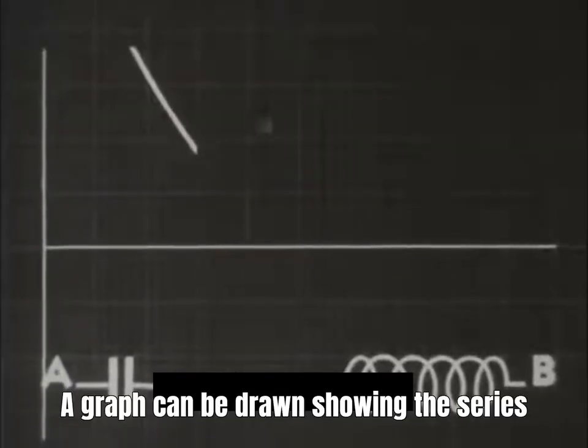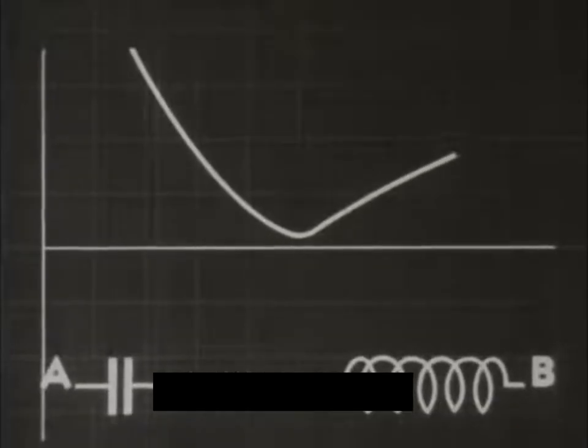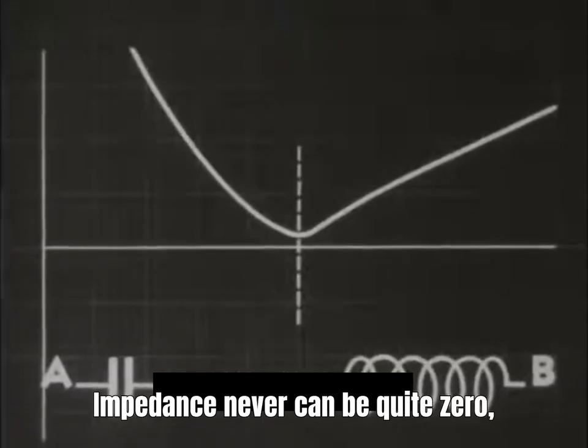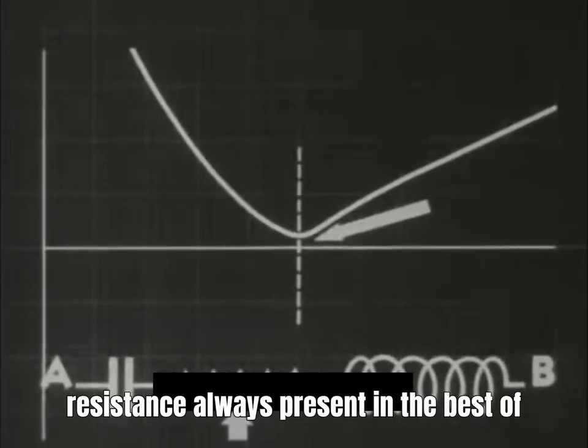A graph can be drawn showing the series resonance in terms of impedance alone. Note that the value of impedance from A to B is lowest at resonance. Impedance never can be quite zero, however, because of small amounts of resistance always present in the best of circuit components.